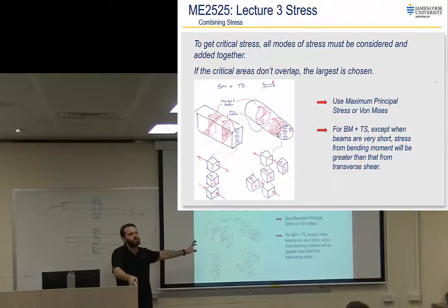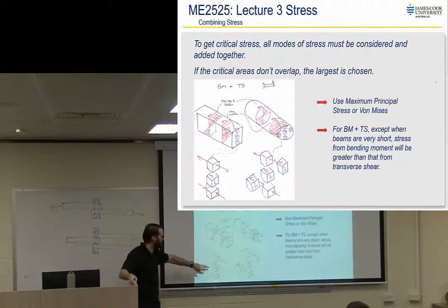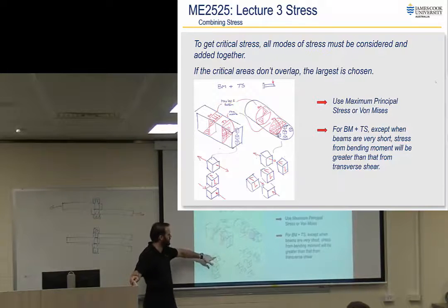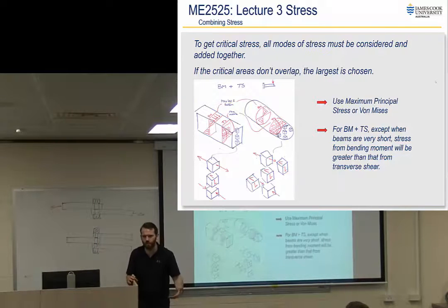But what we need to do is calculate a stress that is representative of a maximum. So principal stress, let's say principal normal stress, that would be that already. This shear one, you'd have to rotate around to a 45-degree plane or something to get what its principal stress is. Then you compare this one's principal stress to that one, and the maximum one's the one you use. Whereas von Mises doesn't require any of that rotation. You just calculate one stress that's representative of the full 3D stress state, and that's what you use as your comparative mark. All right, but we'll do that.